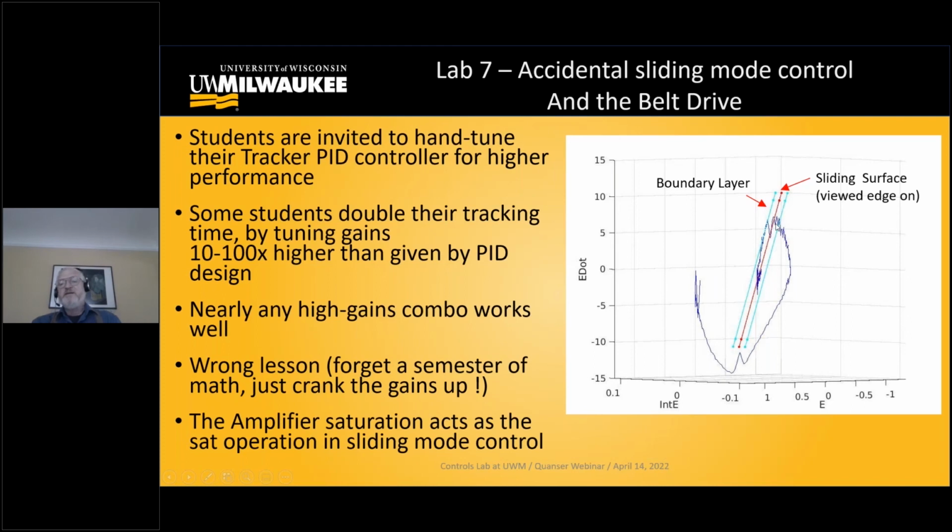As Slotine points out, Jean-Jacques Slotine at MIT was a pioneer in practical sliding mode control, not the first one to approach the mathematics, but really played an enormous role in bringing sliding mode control to practical applications. The switching surface is both a place in the sense that it's a hyperplane in state space, but it's also a dynamic. So any state which is on the switching surface will converge to the origin of the switching surface.